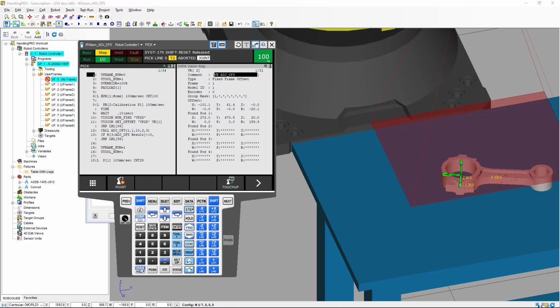In conclusion, you need to be very careful and pay special attention when you configure the user tool, user frame, and the calibration grid frame. There is a way to identify that you made a mistake. If you move your part on the X and Y without any rotation and you're able to get the correct offset data, and then you rotate the part and you get bad offset data, that means your problem is more likely in the calibration grid frame setting.